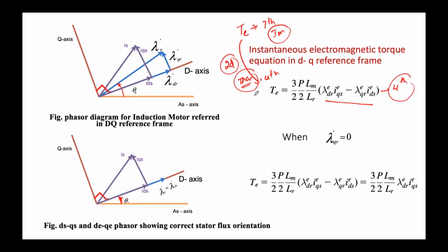This fourth order expression involves rotor flux and stator current. This is the resultant rotor flux. We can resolve it using natural A phase, B phase, C phase quantities. Whatever amplitude and vector you are getting, the same vector we can realize by using Q axis and D axis flux linkage.